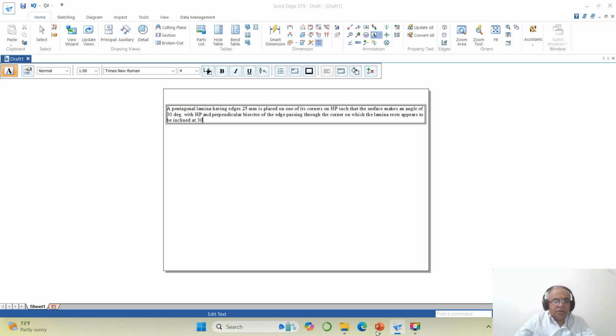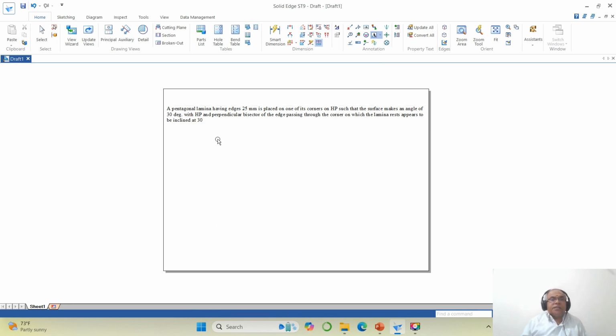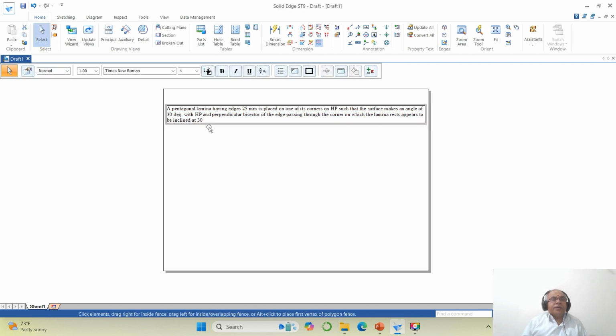For the degree symbol, hold the Alt key and type 0176. So here I will take 30 degrees to VP.